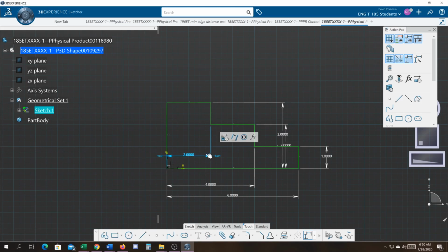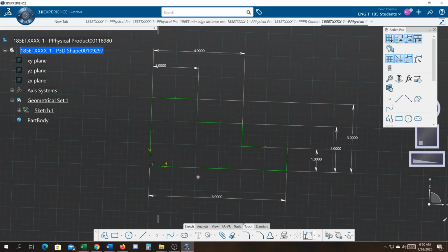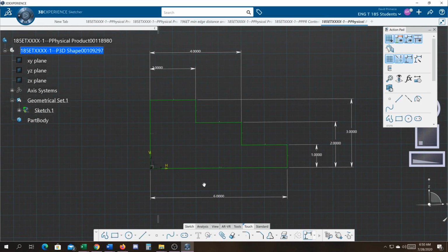Okay, and then you can move out your constraints and do whatever you like. One of the reasons why I recommend building the part off and then linking the coincident, it makes it easier to switch your datums if you wanted to move them around and have a different point on that local axis.